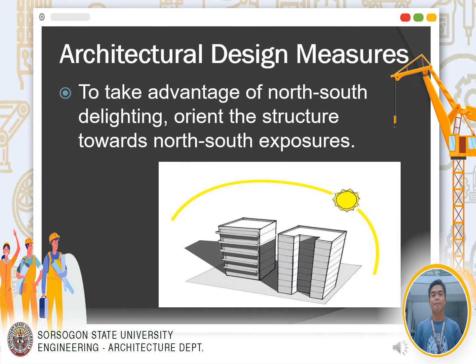It is usually practical to maximize daylighting by orienting buildings so that spaces that require repeated activities and comfort, and where occupants spend the majority of their time, get much southern exposure, while northern light is indirect. It means that it is always in a shadow area, causing spaces to feel dark and cold. North-facing windows receive less sunlight, but the benefit is that northern light is diffused and effectively controlled and comfortable.